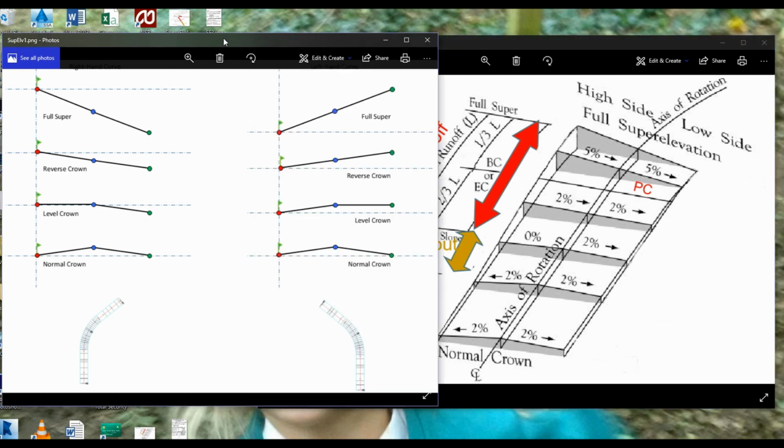So, okay, if we'd be walking through, the road would gently be lifting up on the outer edge until one side of the crown is actually level with the center line level there. So this would be at 0%. And then as we'd go through, we'd end up, they call it reverse crown there. I'll call this continuous crown.